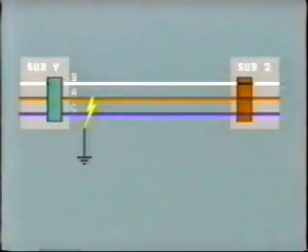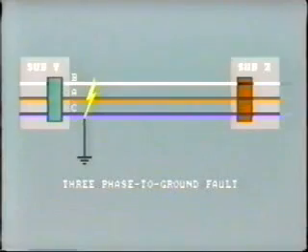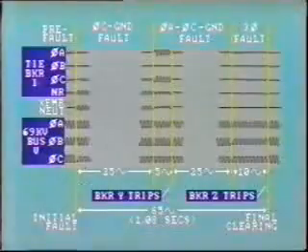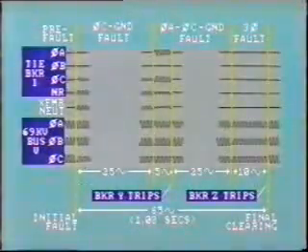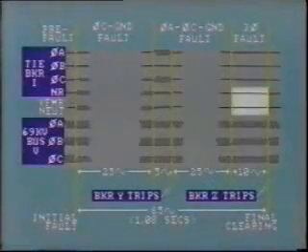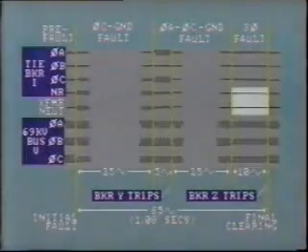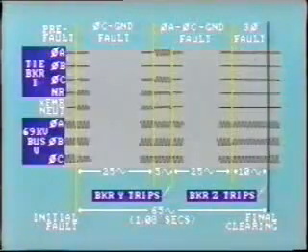At this point, the fault again changes. The A phase conductor now burns open. The tree contacts B phase and falls to the ground. But all 3 open conductors are now in contact with ground, resulting in a three-phase-to-ground fault. For the next 10 cycles, we have a balanced three-phase fault. You can see this from the three fault currents in the tiebreaker and the fact that neutral and residual currents are now zero. Breaker Z at the other end of the faulted line now trips to completely clear the fault.